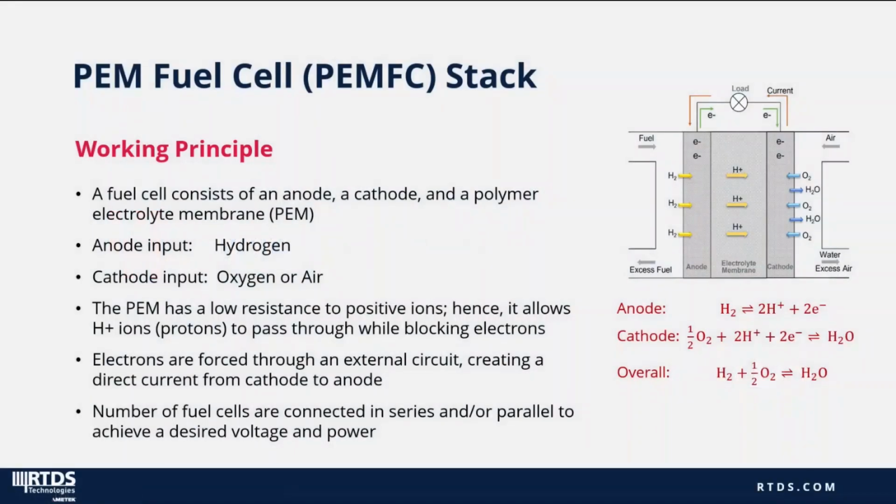The first component is the PEM fuel cell model. The basic structure of a single fuel cell is shown in this figure. It consists of an anode, cathode, and electrolyte membrane. Hydrogen is provided to the anode as the fuel. Oxygen or compressed air is provided to the cathode.